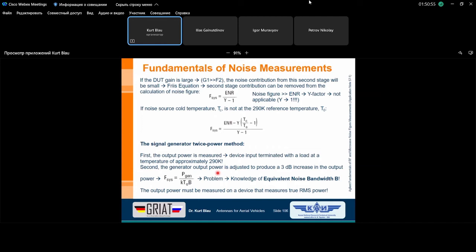And what we have to do now is increase the input power in such a way that our output power, regarding the state before, goes up to twice the value. This means our power meter now shows twice the output power. Again, first the amplifier is switched on. At the output, we have a power meter which can measure the output power of a noise signal.